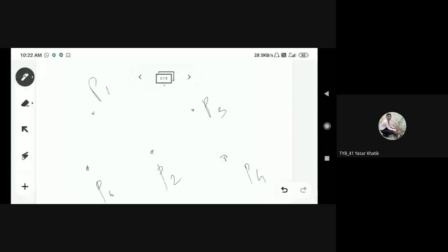Basically, that curve is just taking only 2 points at the initial level. Suppose after that I want to change the nature of this curve. By using the control points P1 and P3, it is easy to change the nature of the curve. By using just these control points, you can drag the curve in your required direction.